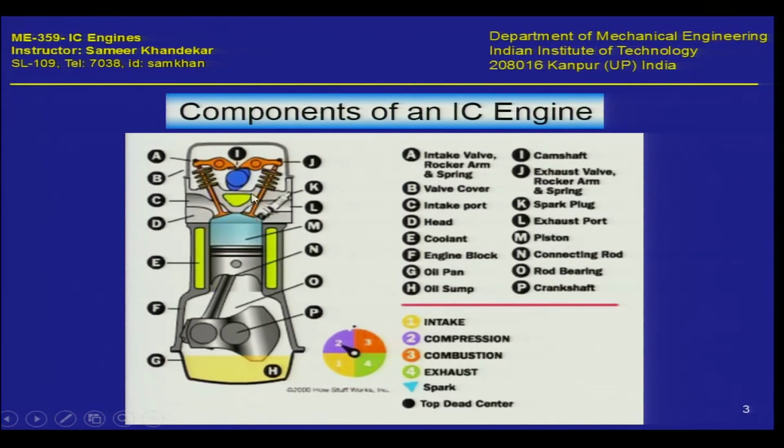They also cool on the top near the cylinder head. They need to cool especially the exhaust valve here, also the inlet valve, because if the inlet condition becomes very hot, then the density of the air which is coming in actually reduces, and that thwarts the amount of air which can be inducted inside the cylinder in a given stroke. So therefore you need to cool this area, you need to cool the exhaust valve, because hot expansion gases are going out from this particular port from here.